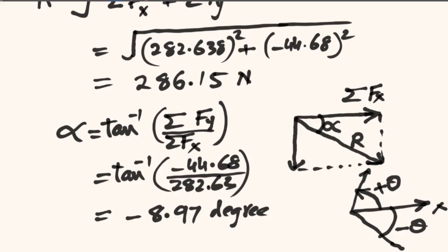That also I explained what coplanar and concurrent forces are, by resolving these forces into components, and these components we take in x direction and y direction, and then we combine them mathematically, that is algebraically. We take sigma fx value and sigma fy value. This concept is extremely important in engineering mechanics and structural analysis, where you will be dealing with so many forces acting in different directions.